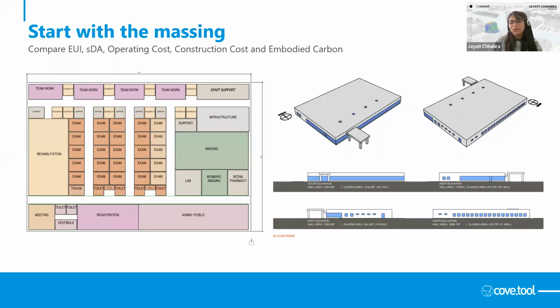Also, they tried to be realistic with the glazing percentages for each elevation based on the previous EUA projects. So the following images show the 3D views and each elevation of the case study. For the south and west facade, they have continuous glazing with a window to wall ratio between 36 and 50%, while east and north elevations have punch windows with a lower window to wall ratio ranging between 17 to 19%.